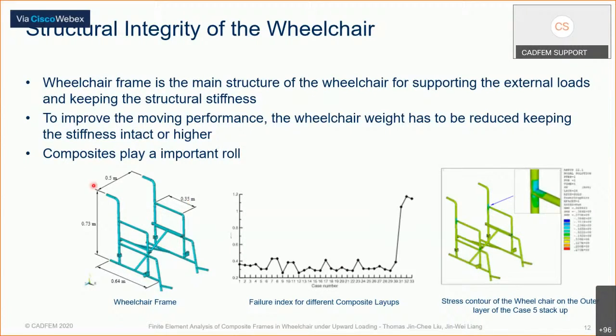Similarly, in order to understand the wheelchair integrity itself, you can model it as aluminum or steel and see what the integrity will be. How will a wheelchair's frame deflect when a person is sitting on it multiple times? What will be the life of the wheelchair, by doing a fatigue analysis? So different kinds of analysis can be done in order to understand this.